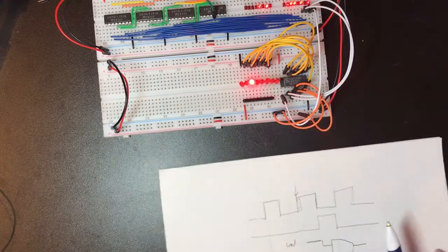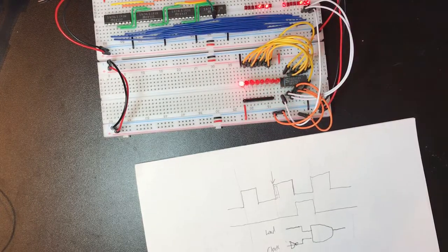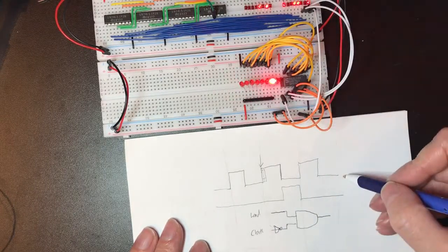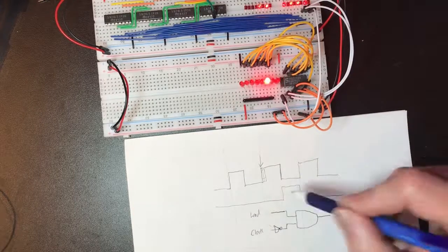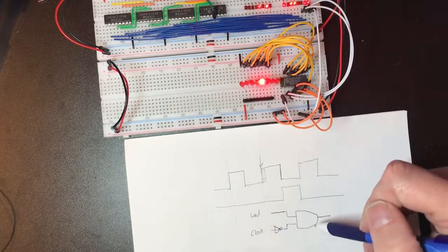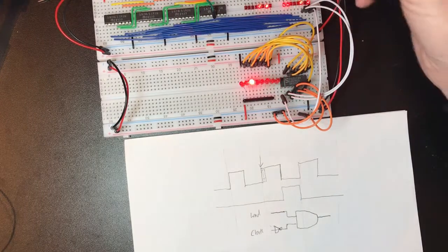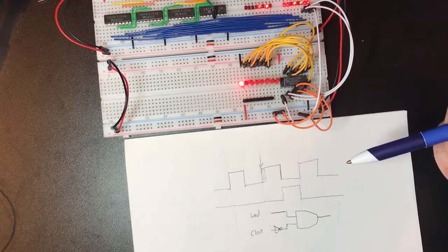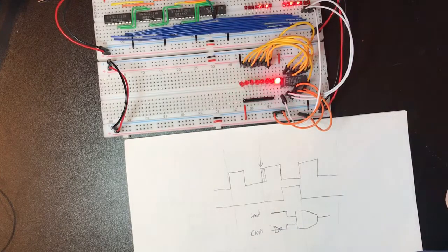But this does mean that in this version of the circuit we would end up with 8 output lines and 8 AND gates. Now, that's not actually the end of the world. If we had to do that, that would be fine, because we know that we actually get a fair number of the simple gates on a 74 series chip. So we'd only need a couple of the AND chips. But there's actually a much easier way of doing this.